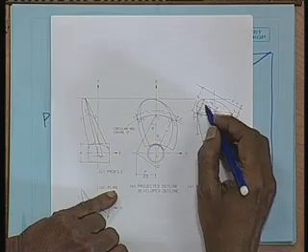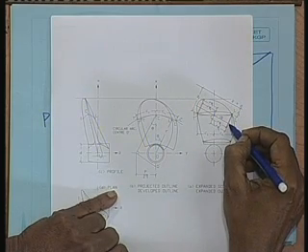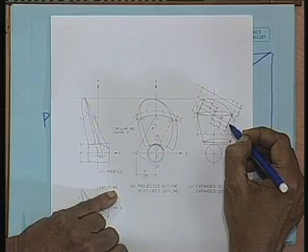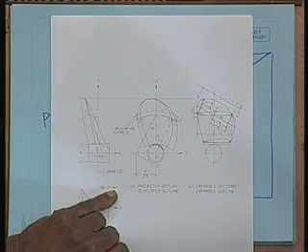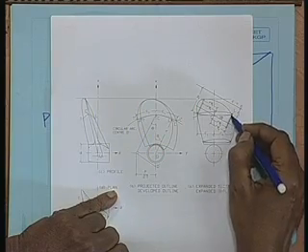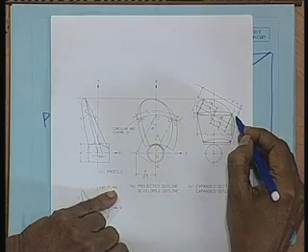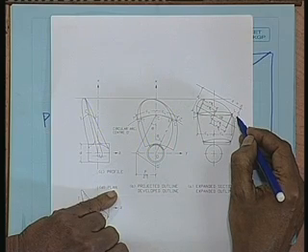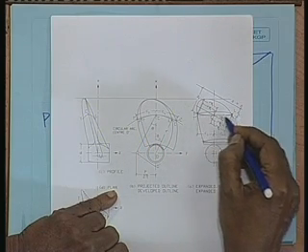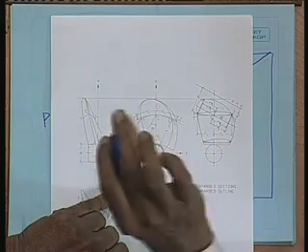So this is r theta T and this is r theta L. Along that diagonal line at angle phi, when I bring it to the horizontal plane, it becomes a longer line. Do you understand? So this section is now known as the expanded section drawn horizontally.